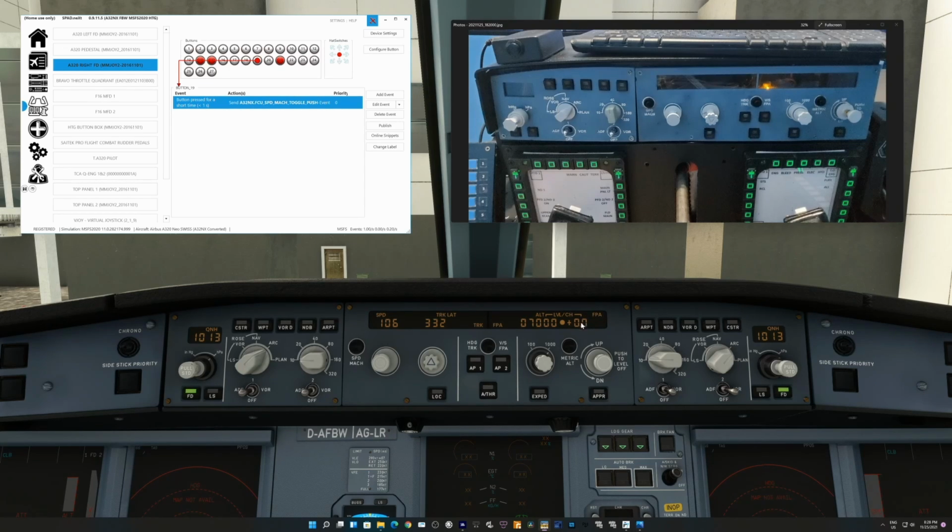Okay, so this one here you change into angle, I think this is in angle, right? 3 degree path angle. Let's say you want 3 degrees. This is usually very useful when you're doing an RNAV approach. So you set, sorry, not plus but minus 3 degree, or descent by 3 degree. Then it will follow the flight path angle of 3 degree, for example. Or sometimes in the chart it's set for 2.7 degree, then you can follow the flight path angle as you require. So the aircraft will descend with this angle in flight path angle. Usually this one is for normal descent and ascent. I think during flight we can change this one, but not in static or on the ground.